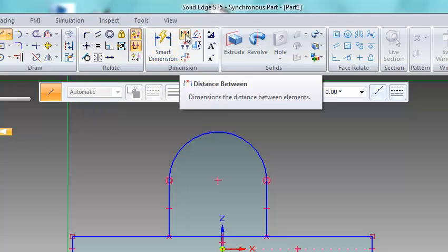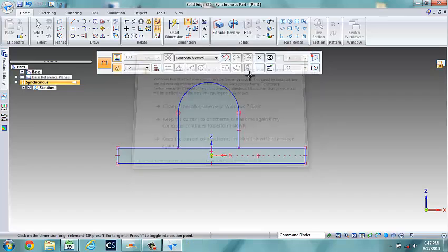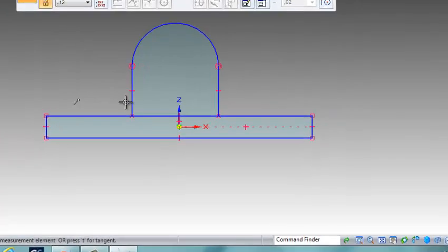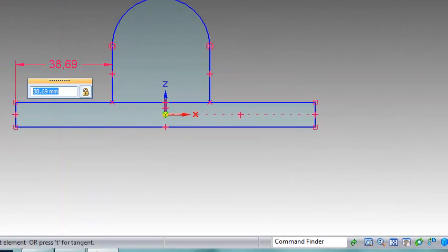I just want to do a dimension. So if it's 60 from 120, it'll be 30 over. So I know that the dimension from this point to this point should be 30. So I'm just going to key in 30.